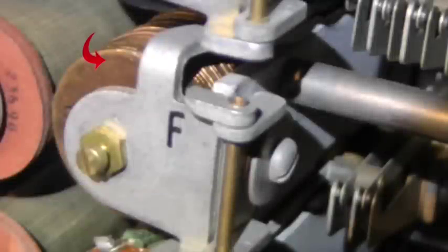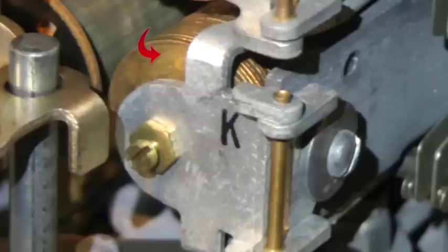The delaying devices for both the F and the K relays are copper slugs mounted around the armature end of the iron core. These delaying devices also work using the principle of Lenz's law. When the relay winding is first energized, a magnetic field begins to build up. This induces a magnetic field around the delaying device that opposes and therefore delays this buildup.